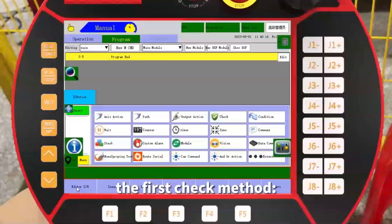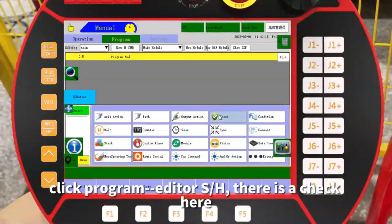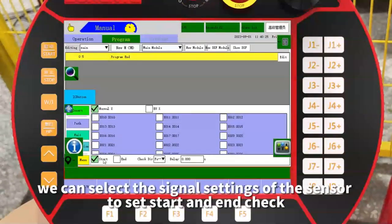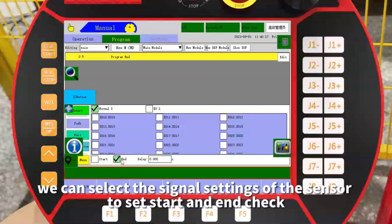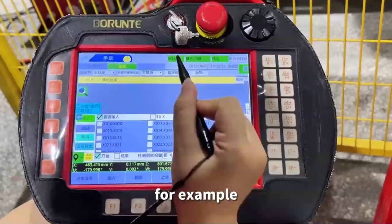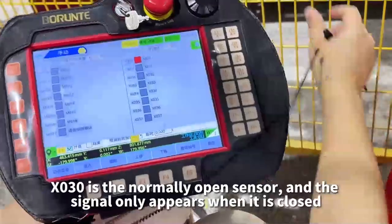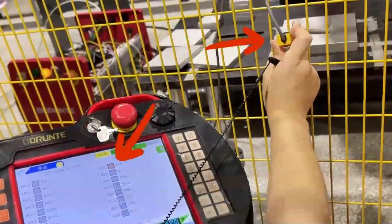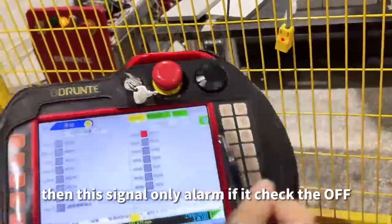The first check method: click Program, Editor, and there is a check option here. We can select the signal settings of the sensor to set start, and then check. The robot alarms when it checks an ON or OFF signal, and delay, to complete the continuous signal check. For example, X030 is a normally open sensor, and the signal only appears when it is closed. Then this signal only alarms if it is checked as OFF.